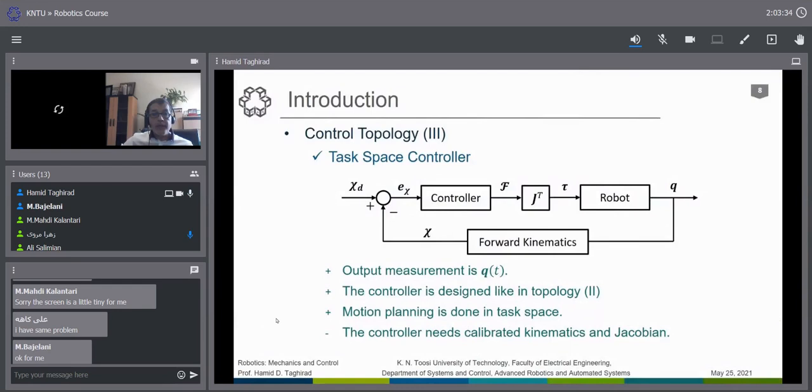In practice, what are the main sources of torque disturbance? They are in task space. Depending on whether you have some disturbances on your links or your joints, then it is in the joint space. But usually we have some friction at the task space, or the payload will be changing. You pick something up, so the robot payload will change. We don't call the payload a disturbance; we distinguish that. Even in the simulation, you change the payload, you change the end effector mass, and this is quite possible. If you change the mass, your dynamics is changing, and so M and M hat are not equal to each other anymore. We shall use a robust and adaptive controller for that.